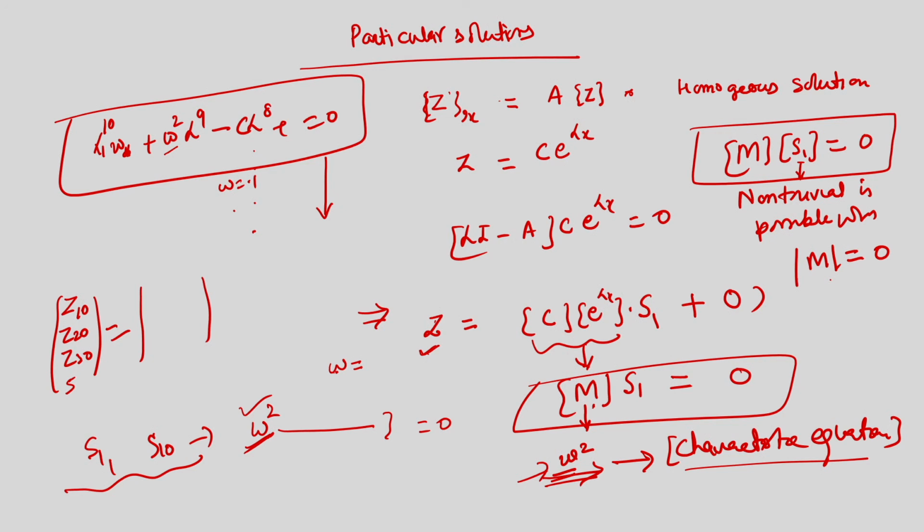Generally for these cases we try to take the guess from the simply supported case, since a simply supported shell will have a higher natural frequency compared to a clamped one. So, we have to reduce the guess so that we can get the frequencies.